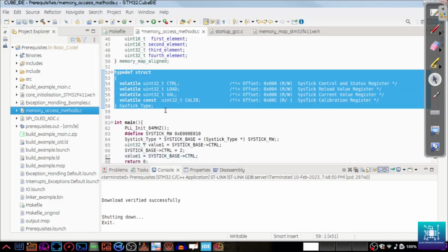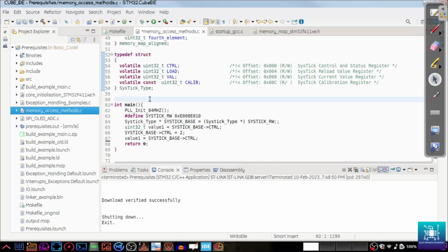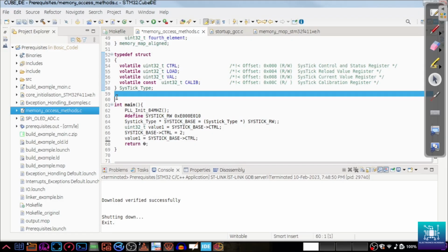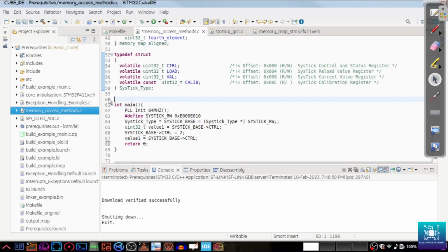file. That's the CMSIS header file, which we are going to reuse after some modifications. So you don't have to write it. And even for method 1, whatever hash defines that we saw will be in header files. We don't have to write those hash defines, that is the base and the offset, whatever we saw. For method 1 is also something that we don't need to write. That is going to be in the header file. So I would not disadvantage method 1 so much. Method 1 is more precise. You don't need to worry about padding and stuff like that. Here it's done through the structure.